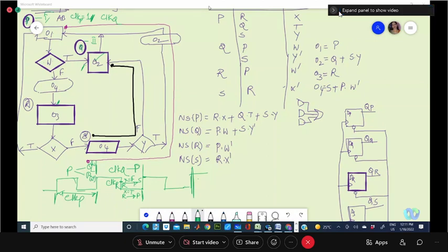No two stable state outputs will happen in the same clock. That is a point you can remember. No two stable states will be generated in the same clock. Only one stable state. That means where the clock has started, for which state it has started, it may at the most take that to another stable state, generating your conditional outputs or testing the test variables or generating the unconditional outputs.